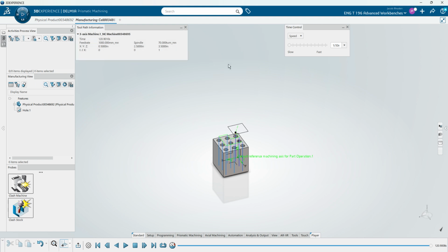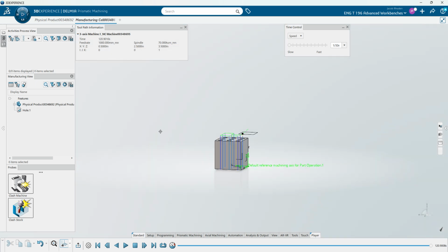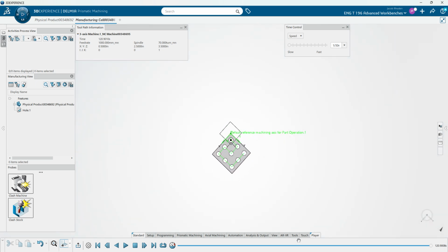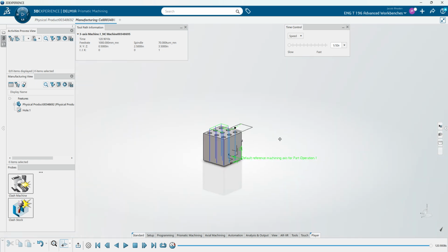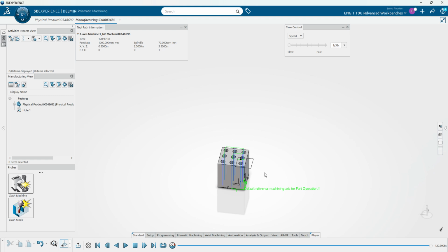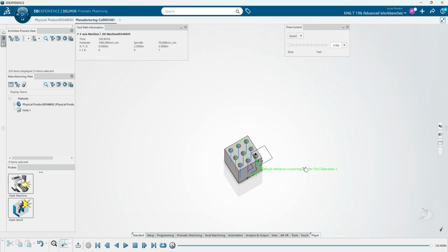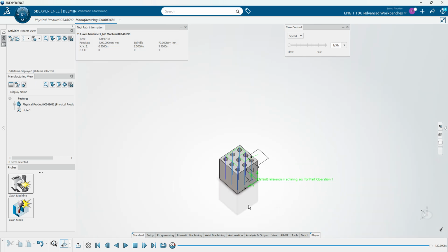Obviously you could go in and change the speeds and feeds and the rapid rates to just make that fly by. But that's pretty much, once again, how you do the whole drilling thing, all the different drilling options. And another thing with drill options, like the actual tooling options, instead of maybe using something like a high-speed steel, you could get a carbide with through coolant, which would let you lower this time a lot more. And there are many, many different options with tooling and all the different companies that might be able to take you to getting that time down, because that's obviously where a lot of the machining money is, time.